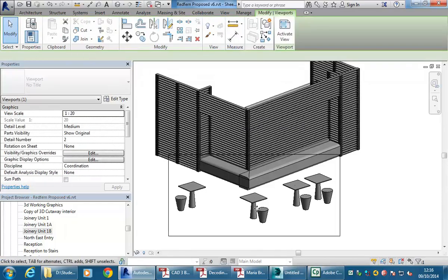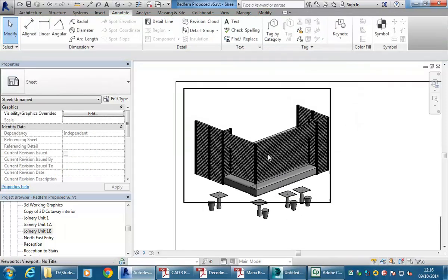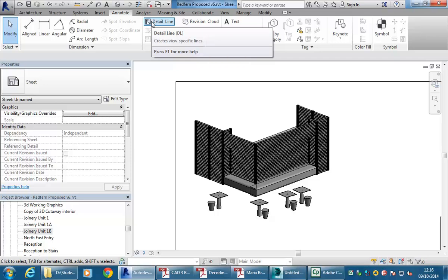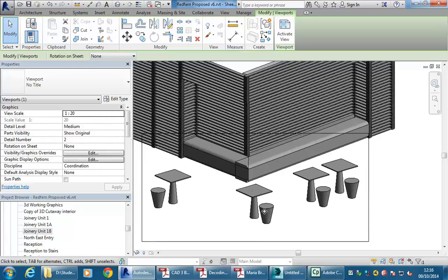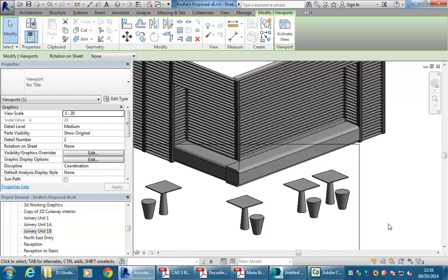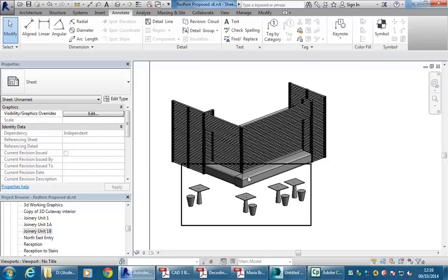But hopefully you can see from that how you have the exploded isometric views that you can have broken apart and then connected with a series of lines. So the dashed lines that you have, you can just use detail lines for those. You know what I'm talking about? So that's basically their final position, but you can easily have those separated. Probably not the best example, but when you've got things that need to be exploded, that's all you need to do.